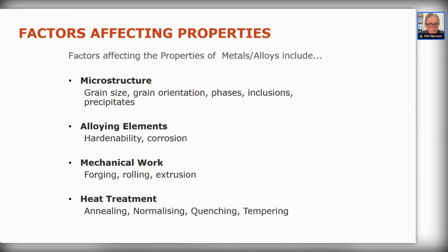Also, we've only covered hot work, and we have cold working of metals. When you have cold working of metals, what this does is something called strain hardening of the material. The strain hardening increases the mechanical properties, increases strength and yield strength, etc., at the expense of elongation and toughness. So we then do a process called heat treatment, called annealing, to recover these properties. But every time we heat treat, if we do it correctly on cold worked materials, we refine the grain size.